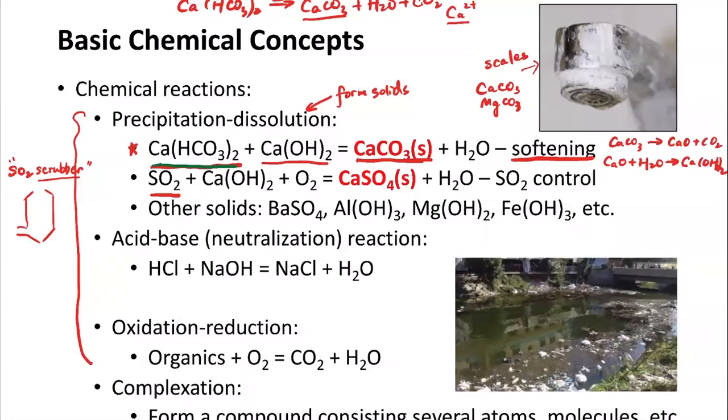What happens is we introduce the polluted gas into the reactor, right? They're in the gas phase. At the same time, you have spray nozzles that spray down solutions. So this is literally a shower for the sulfur dioxide. For these water droplets, what people introduce is again calcium hydroxide. So you have a feed that goes into the pipes, and then you have the water dripping down. The sulfur dioxide is going to react with the calcium hydroxide,